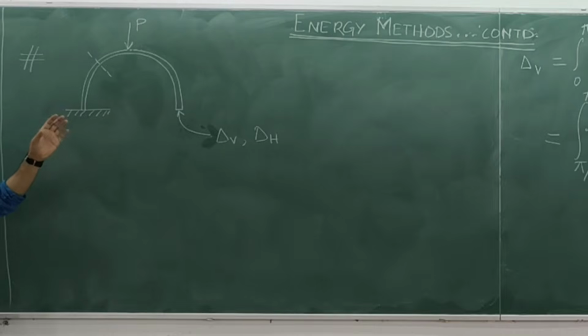Whenever you encounter a question like this, you first ask yourself: at the location where the deflection is desired and in the direction in which the deflection is desired, do you have point forces available? You don't, which means that you have to introduce fictitious forces. Almost algorithmic.